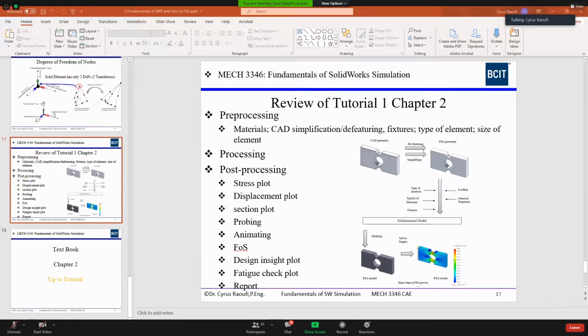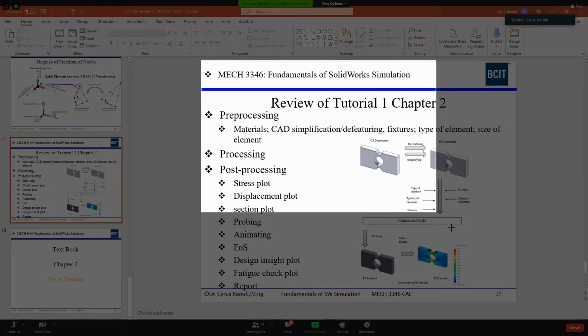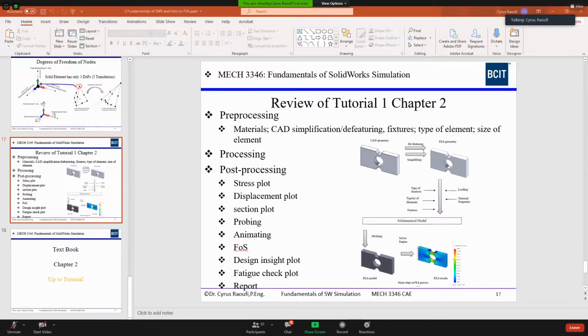If you didn't do a good job here, again, you define a mathematical model, but it's not the problem that you had. You define a problem which is different from your real life problem. But from this point, SolidWorks is going to take care of the rest, and is going to do discretization, and then solve the problem and give you some numbers. All right, be careful with what's happening here. This is what I called last time the journey from CAD to the result, which is the FEA journey. And that slide is from your textbook anyhow.